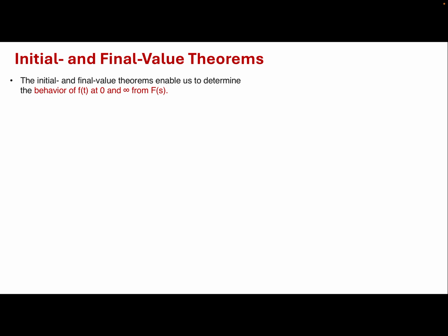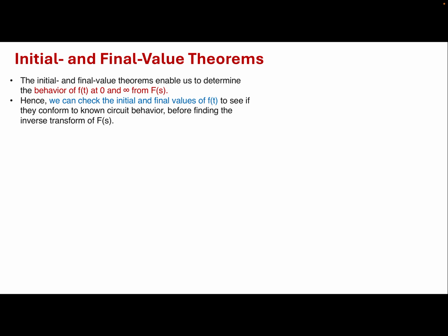The idea is that you start with the circuit, you get the differential and integral equations, and you convert that into a Laplace transform, F(s). Before you inverse transform it, you can work in the s domain with s F(s) and figure out what the time domain responses are at 0 and at infinity, their initial and final values, by looking at the function in the s domain. We're going to find the behaviors of f(t) at 0 and infinity while playing around in F(s). In this part of the lecture, I'm going to derive those things.